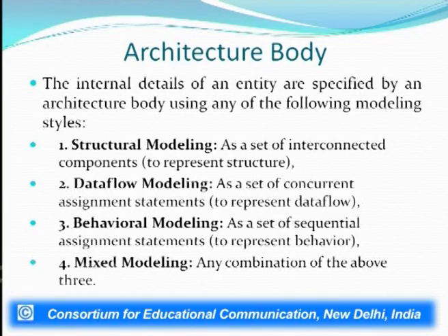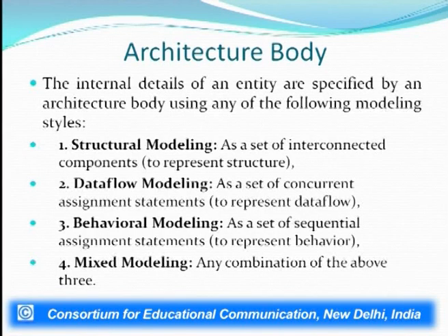Now, architecture, as I mentioned earlier, gives the internal details of an entity. That means the black box that we were considering when I was discussing the half adder, what is inside that black box is dealt with by this particular architecture body. The architecture body will be specified in one of the following methods: structural modeling, data flow modeling, behavioral modeling, or a mixed style of modeling will be used to describe this architecture body.